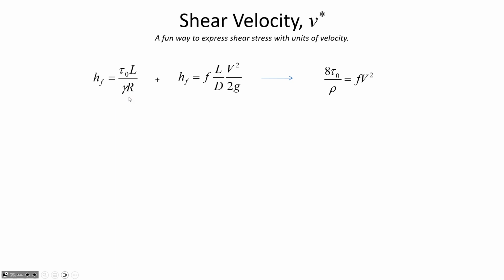And so this is the real way to measure head loss due to pipe friction, but we're not able to use this equation very often because it's not convenient for us to directly measure shear stress. So what we instead do most often is use an empirical estimation technique for determining how much head loss is due to pipe friction. That's based on some parameters that we can measure directly, like the velocity of the flow, the length of the pipe segment in question, and the diameter of the pipe. And then there's some friction factor, which has been derived from lots of observations.